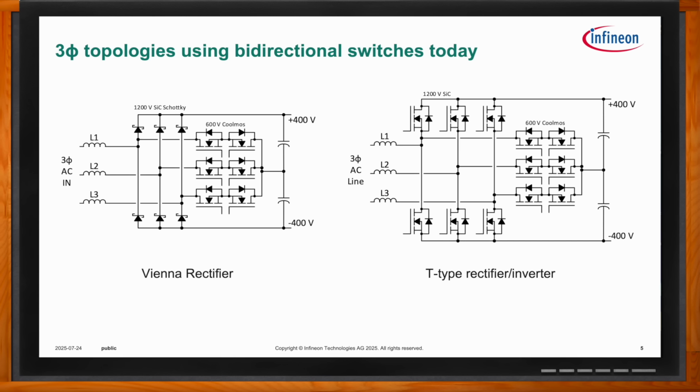In the US, we have what's called split phase, which, technically it is single phase, but it's often treated as two 180-degree out of phase 120 volt. And so you have a 240 volt split phase. And absolutely, in that case, you just take exactly this topology, only get rid of L3 and all of those components, so you have a two-phase system.